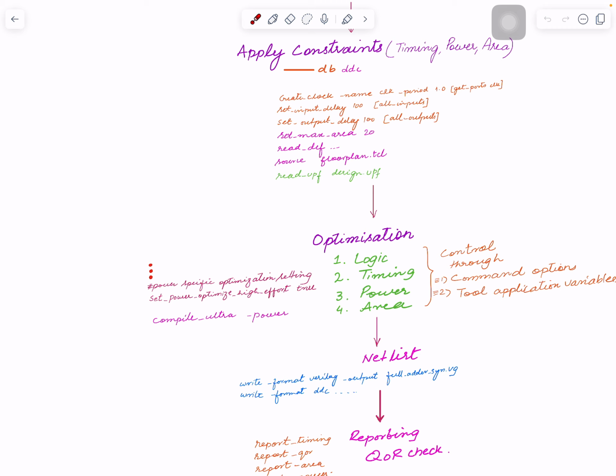For your block, a setting might give you a very good result, but exactly the same setting might not give another person in your team the same kind of QoR results, because the logic inside is very different, and how the tool optimizes or creates it might be very different. So creating a flow, your design specific recipe, is always the first part in physical design. You start with a skeleton flow, a reference flow, and then you start changing options or different commands that you use, and that might work really well for your design.